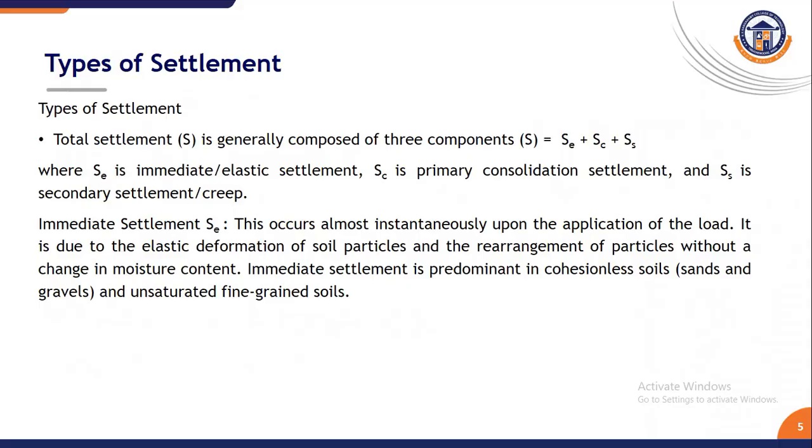The first is immediate settlement, which occurs instantly upon application of load due to elastic deformation of soil particles without any change in moisture content. It is predominant in sandy soil and unsaturated clay. One example is when a temporary load such as construction equipment is placed on sandy soil, the ground settles immediately and stabilizes quickly.